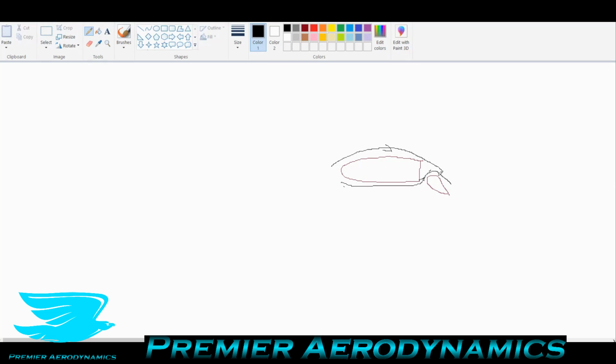And the reason why it's important is because the top flow here is actually slow moving flow by the time we get to this point. So it's really losing a lot of its steam in the boundary layer. What that means is if we were to continue to go over this other element, what this element will do to the flow will make it stall effectively, because this top part doesn't have enough energy to get over and stay attached. So by introducing this additional air and letting it bleed through this part here, the flow can then stay attached and produce a lot of lift.